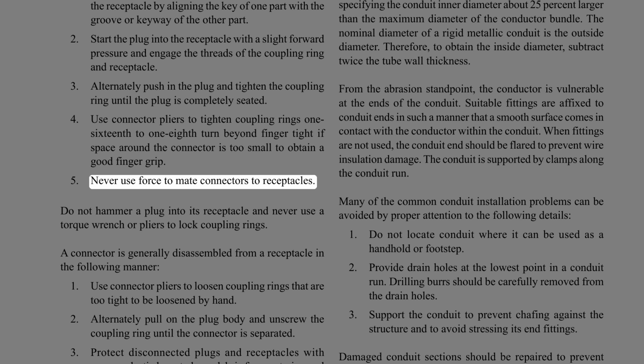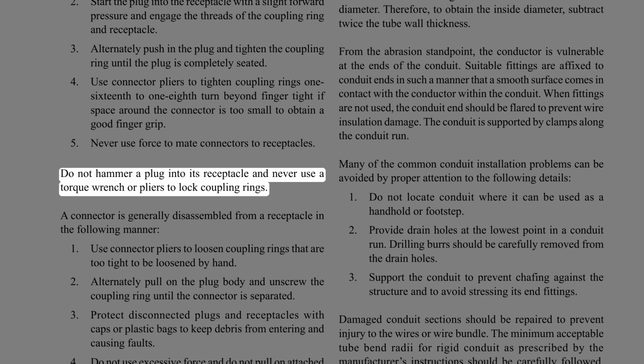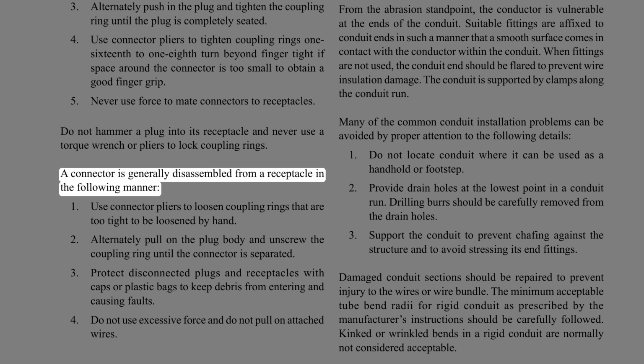Never use force to mate connectors to receptacles. Do not hammer a plug into its receptacle and never use a torque wrench or pliers to lock coupling rings. A connector is generally disassembled from a receptacle in the following manner.